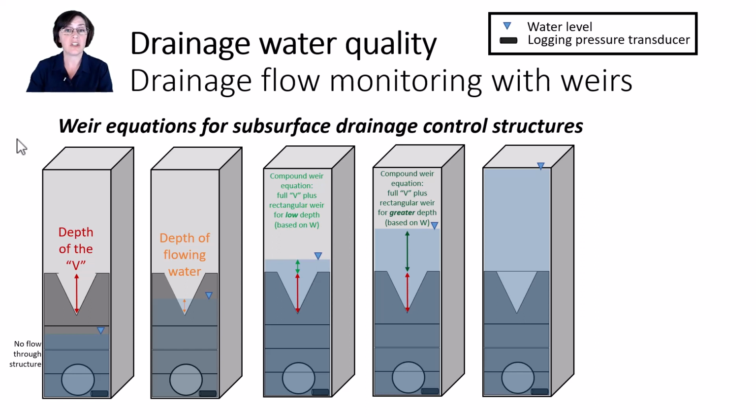In these conditions, you often also have a submerged outlet downstream for the entire drainage system. Here, a weir equation is not valid because there is no air pocket behind the nappe when the weir is entirely submerged on the upstream and downstream sides. It's not uncommon to remove these flooded periods from a data set because there may not actually be water leaving the field due to the submerged outlet.